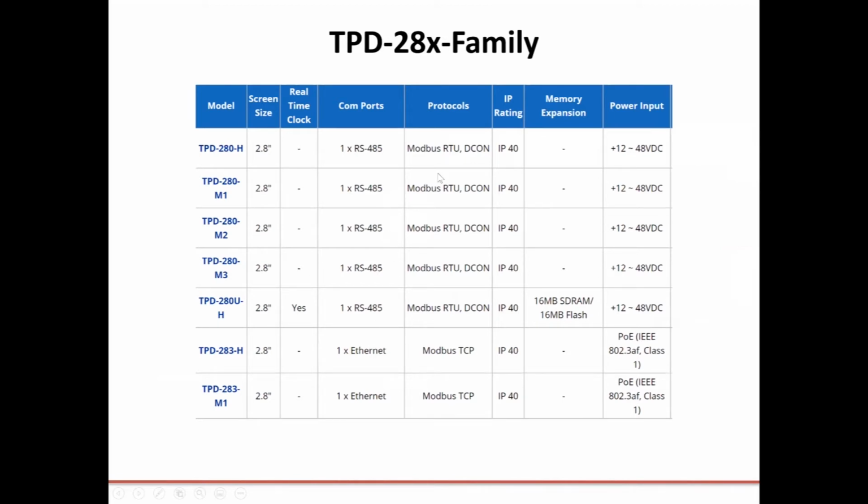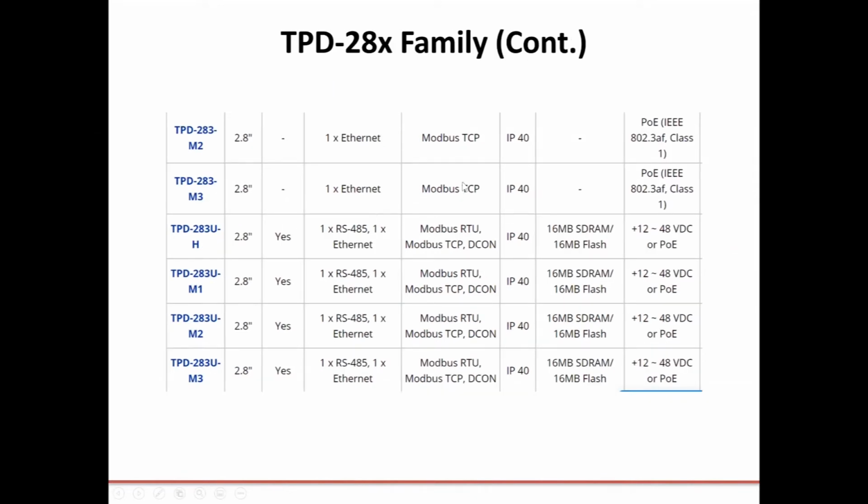So we have a number of options, and the T80U modules also have a USB connection, but that is going to be for software and firmware updates only, so not for communication between the HMI and different modules. And see the end of our selection table here. So we have the Ethernet versions in PoE, and we also have some of these TPD 283 modules, which do have RS-485 and Ethernet.